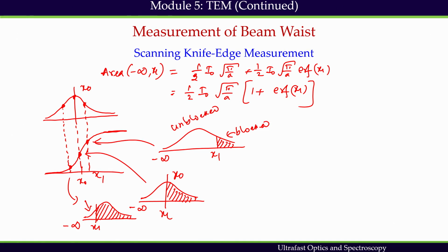And the question is, how do we define the beam size? So basically in the experiment we get this error function behavior. This is the measurement we see, and once we get the measurement done, we can find out from x naught, where the maximum intensity Imax should appear. All we need to do is get, from this Imax, the Imax by E square point.